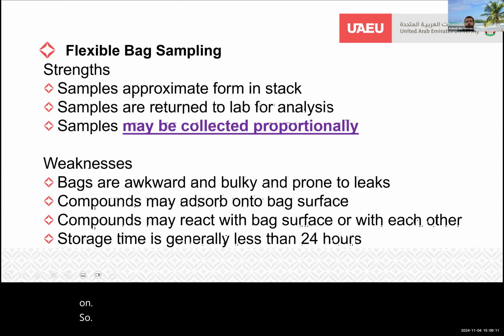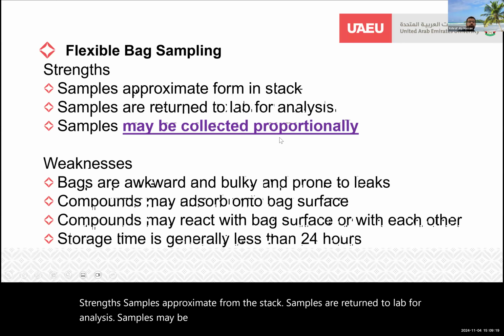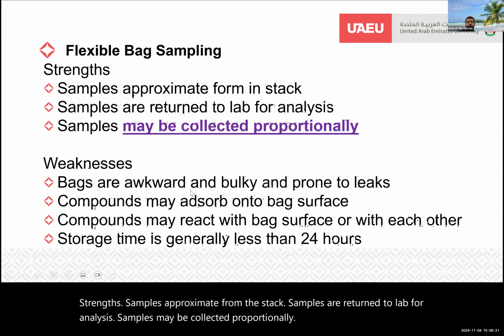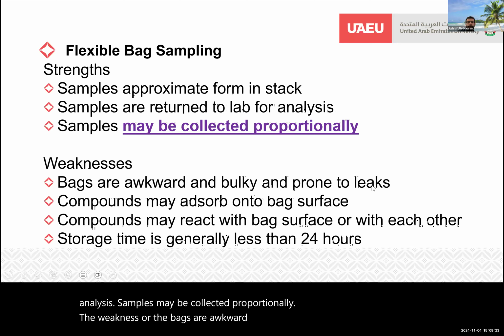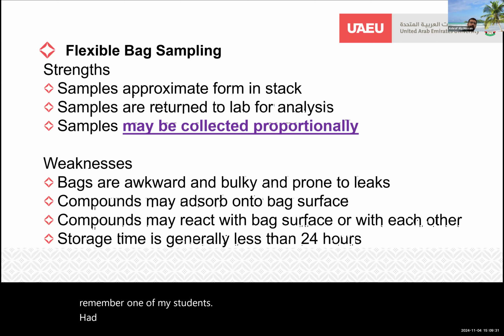Strengths: samples are approximate from the stack, and samples are returned to the lab for analysis. Samples may be collected proportionally. The weaknesses are the bags are awkward and bulky and prone to leaks. I remember one of my students had like 20 bags and the plant was like 6 hours away.